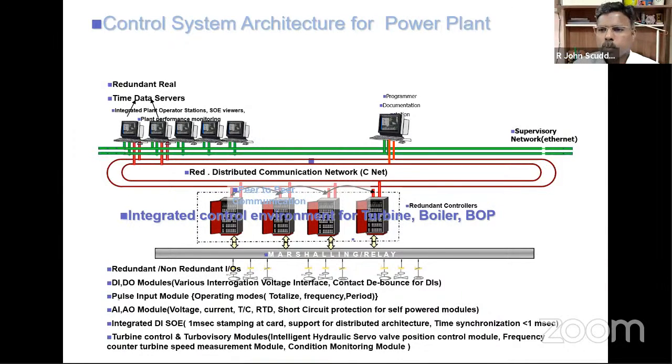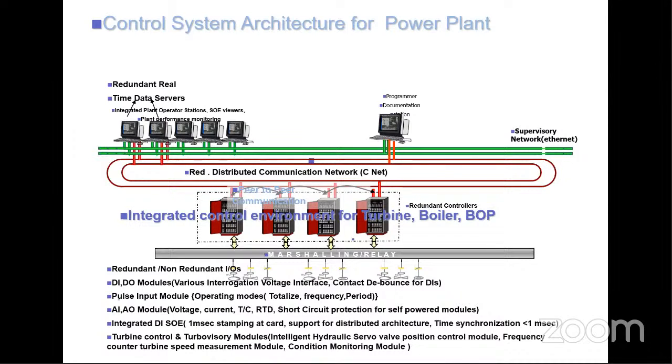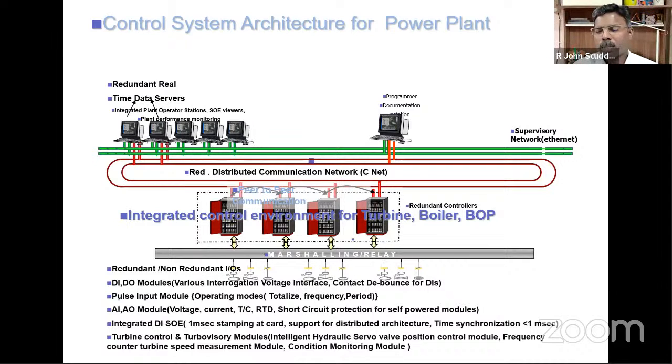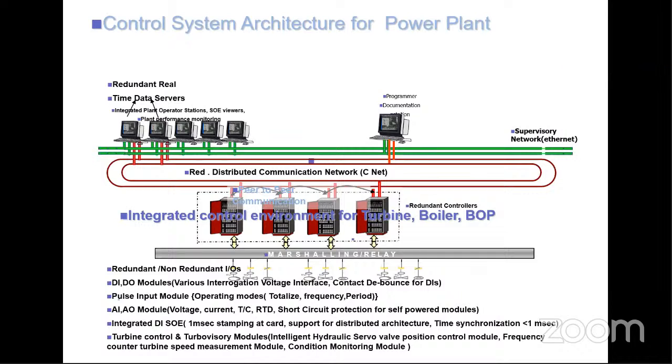No. There are specific function blocks which have the capability of stamping the time, right? Normally all the trip signals don't enter into a single module, because if they enter into a single module, failure of that particular module can create so many tripping causes. So it is all in different modules, but all those modules are capable of time stamping. So time stamping is the key here.